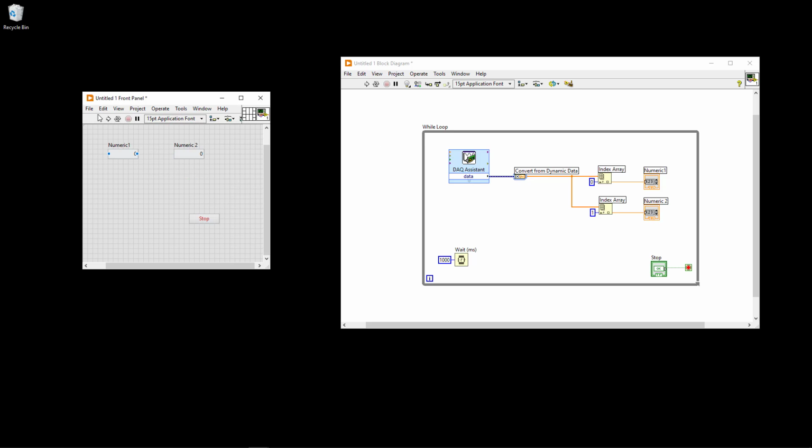And then I can run it. And in my case now I haven't connected anything on either analog input 0 or analog input 1, but I can connect my battery on analog input channel number 1, and then it should here show 1.3. If I put my battery on analog input channel number 0, just give me a second, it should show 1.3 on the left side, while 0 on the right side, which is analog input channel number 0.